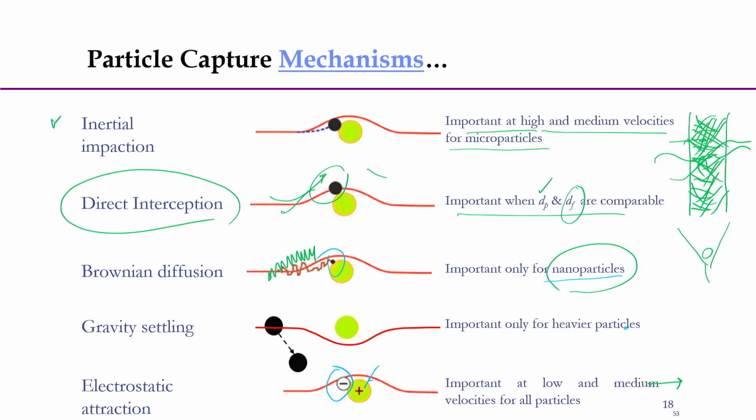So, that is actually an electret filter, and here if we have a larger size of fiber, the coarser fiber, the chances of charge development will be more, and there will be a higher probability of particles getting settled and filtration efficiency will be higher.